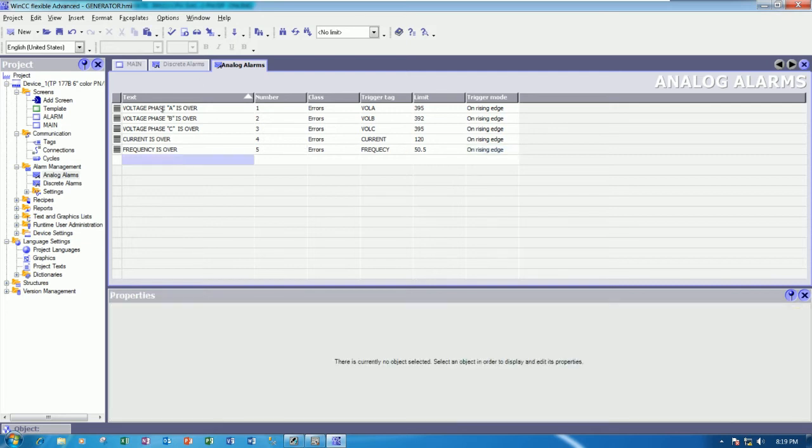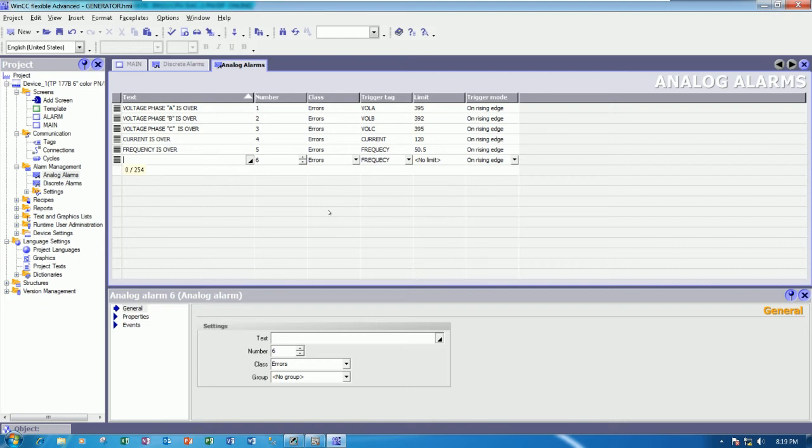Okay, and for the temperature of bearing, yes, or speed, yes, example generator is over speed by sensor 1. Okay, so I will choose the text of speed number 1 here. Example, normally the generator speed is around 3000 before synchronizing, right? So I will choose 315 or 320 RPM.